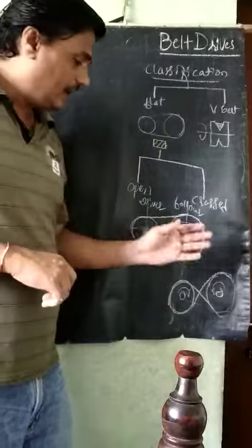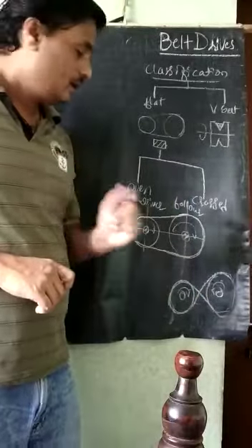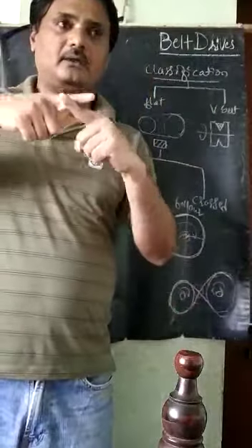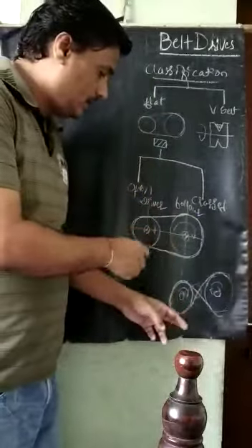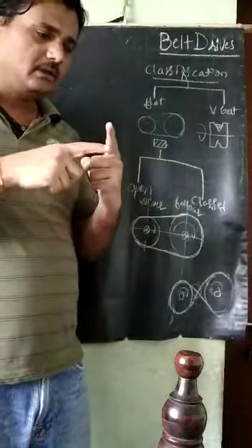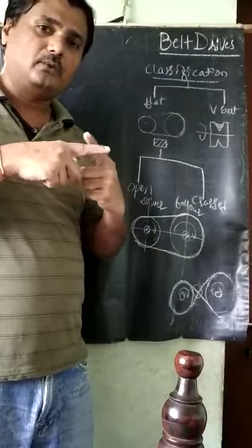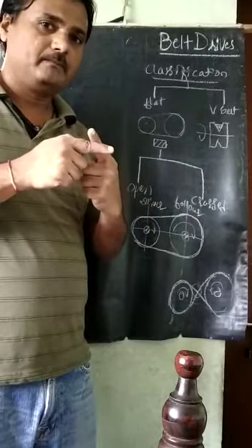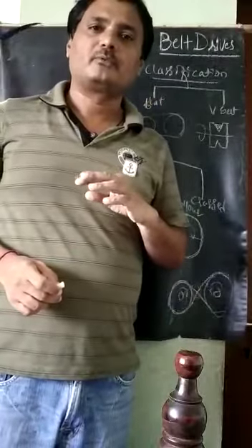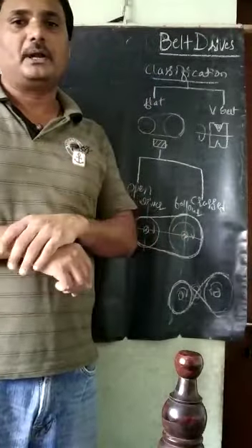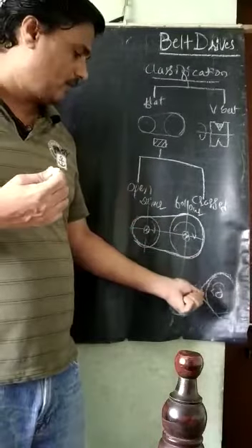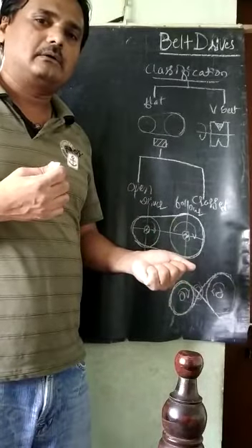Is there any disadvantage of the crossed belt? Yes. The belts are touching each other. When they are moving, they will touch each other, and then definitely wear and tear will take place between the belts. Therefore maintenance problems will occur easily in the crossed belt drive, and also slipping is possible because of the wear, and loss of belt.